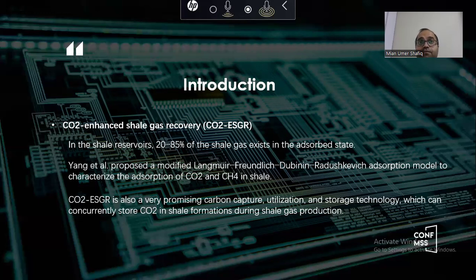This is very important because initially we have to make a shale gas reservoir sector model, and then in that sector model we have to fracture it hydraulically, because we need to fracture the shale reservoir first. Once we fracture it hydraulically, then we have to do the sensitivity analysis on different parameters. For example, the sensitivity analysis will be done on gas injection rate, bottom hole pressure, fracture spacing, half length, and conductivity, which are predictors for training the surrogate model.